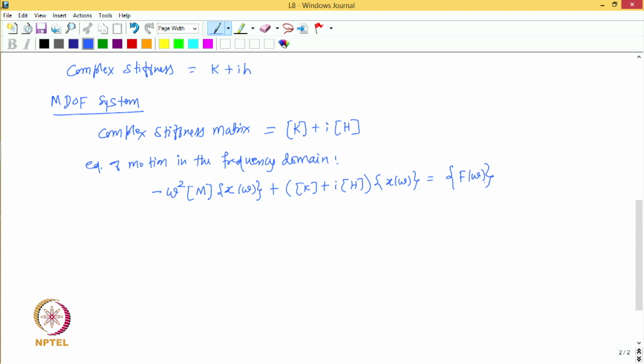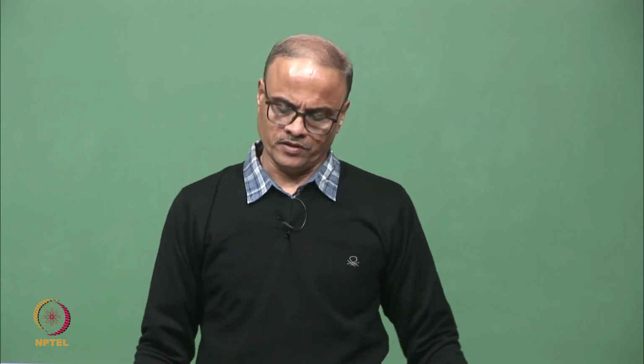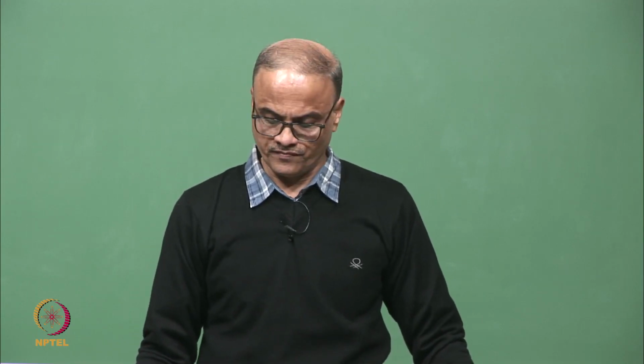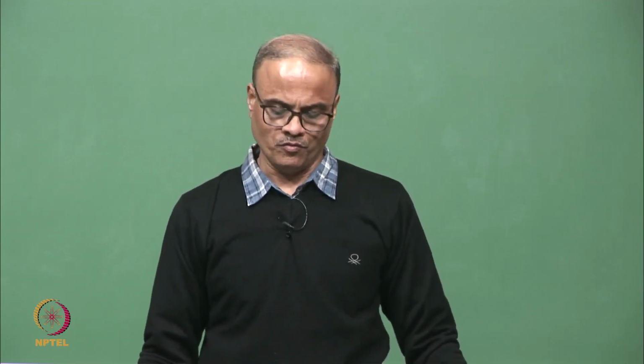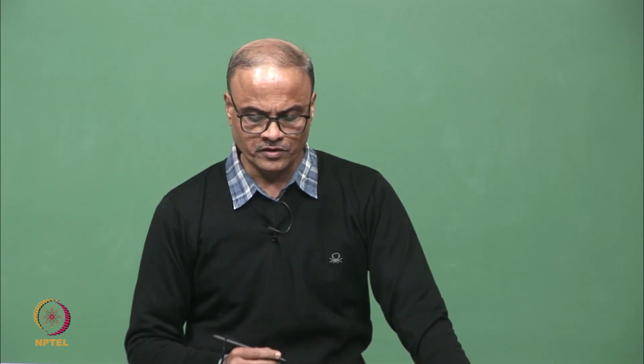So, x of omega is the amplitude of the steady state response at frequency omega, and f of omega is the amplitude of the harmonic force vector at frequency omega. Therefore, this equation is in the frequency domain.